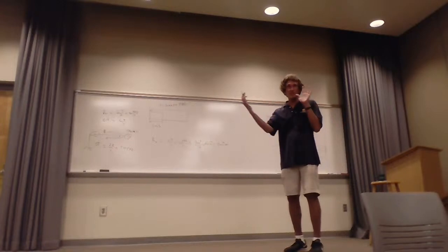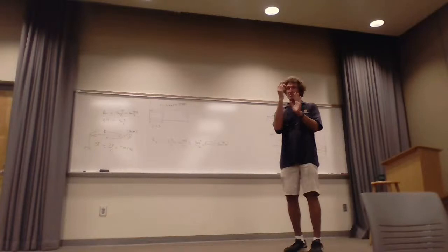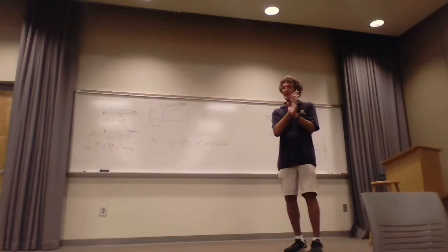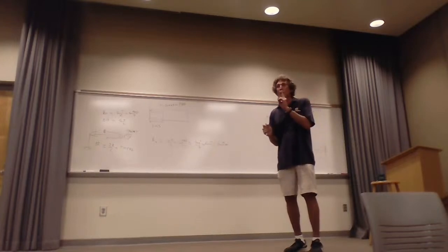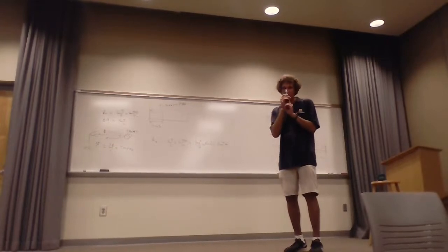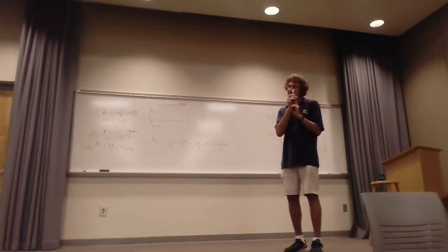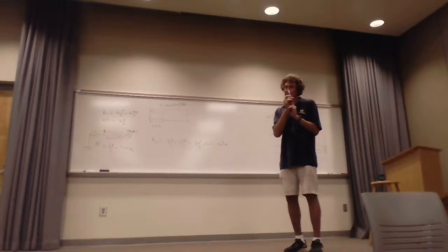They'll show you this, where you got one pulse coming in, you got 2 targets, right? Pulse hits the first one, starts reflecting back, still hasn't hit. Hits the second one, starts reflecting back. If you take C tau, that has to be twice the distance, because before the pulse stops on the first one, the second one can't have a reflection back on the first one. This isn't coming out real well, but do y'all understand what I'm saying? Yes. And it's one of those things you can look at a simulation, it's pretty cool.